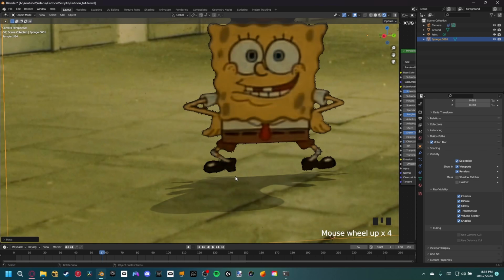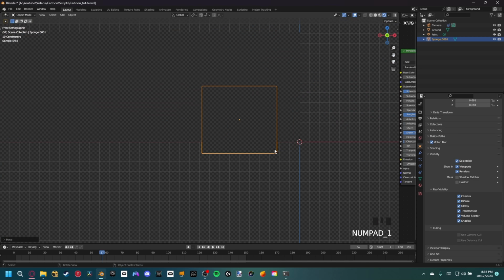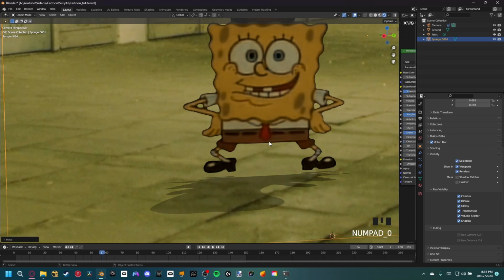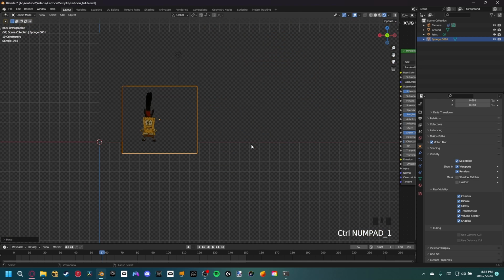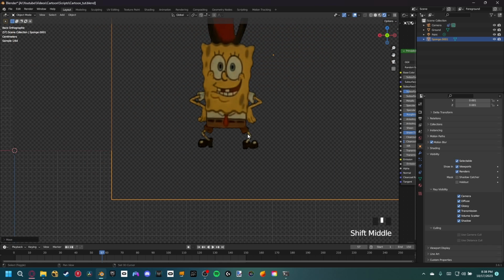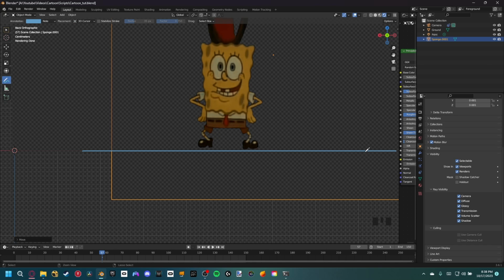What is very important to know is that it's not perfectly straight right there. And so what we actually want to do is go ahead and make that perfectly straight. A workaround I found to do it is to come out here to the side view, hit T up there, and then go to the annotate tool. I want to go on our floor plane, so right here, go ahead and click, and if you hold Control, it actually makes it a straight line. I basically want to draw where the ground plane is. So right there is our ground plane.